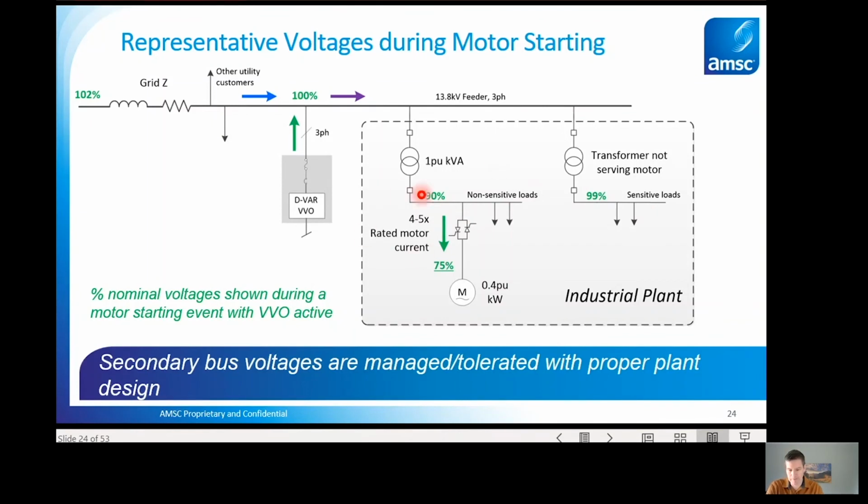So basically, we see that the voltage drop across the transformer is generally not a problem at all. And the advantages of having that medium voltage protection really are strong because then any other transformer, any other load on that circuit is fully protected with that medium voltage application.